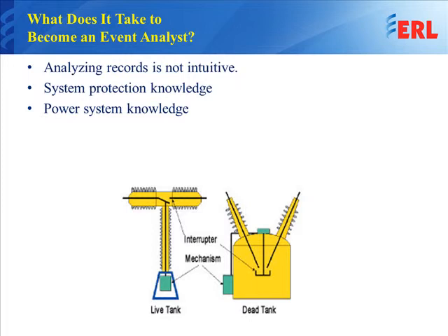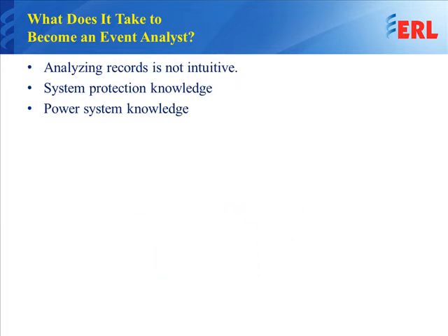Usually the time delay of a breaker to open its contacts is 3 to 4 cycles, depending whether it is an insulator type or oil type. Now if a certain breaker is opening in a longer time than this, then we might have a problem. And the traces can tell you when that breaker opens or closes.